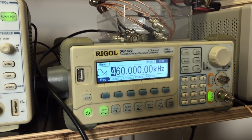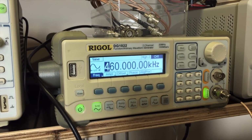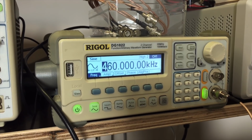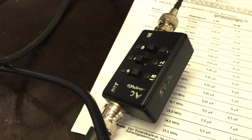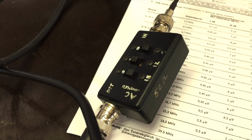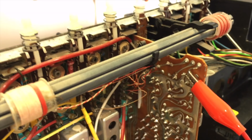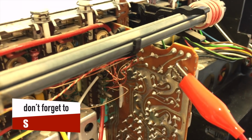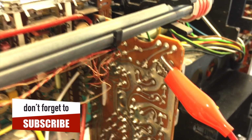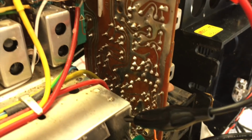So what I've done is I'm feeding a 460 kilohertz signal at the lowest level that I can get on this signal generator, which is 1.4 millivolts RMS. I'm feeding it as usual through this adjustable attenuator. I can get 18, 12, 6, or the sum of any of those attenuation. And I'm feeding it into there, which is the input to this board, which is on filter 17, which is effectively the start of this filter chain down here.